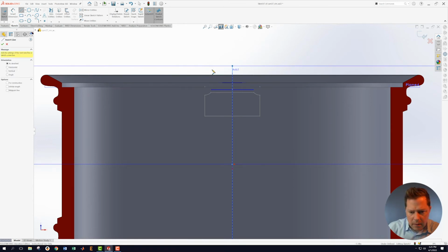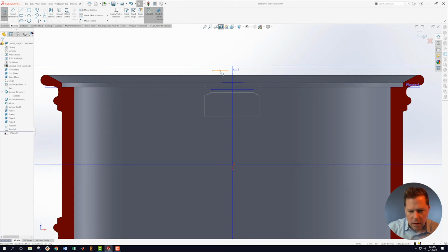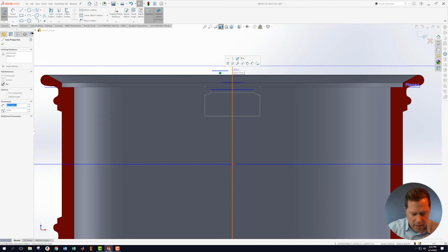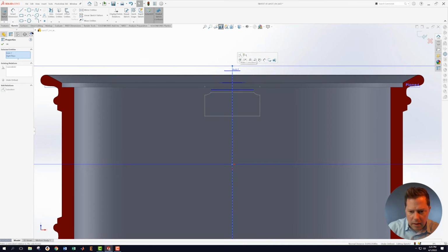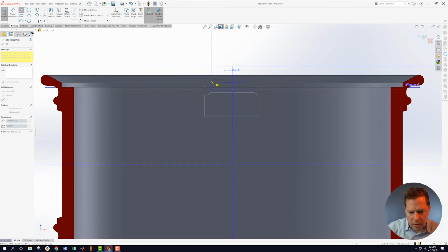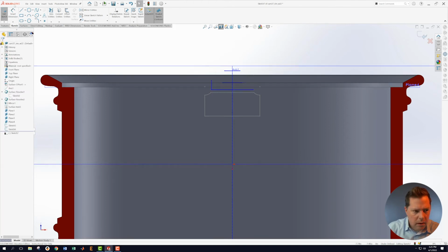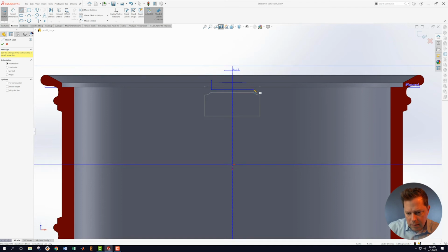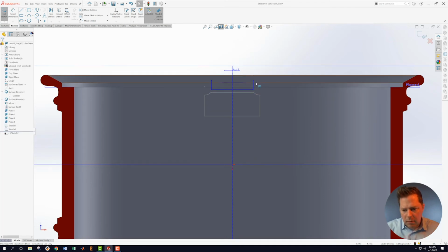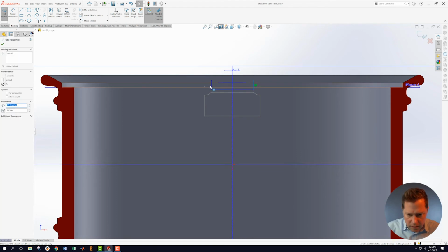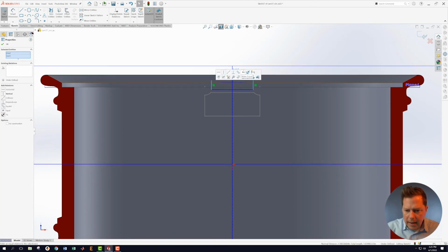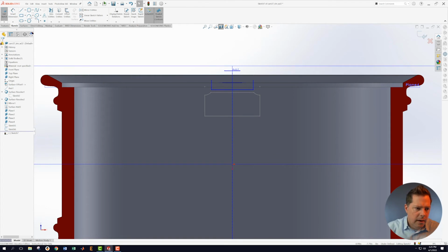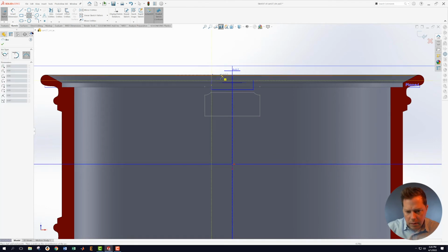Okay, I'm going to do the same thing at the top. Okay, I'm going to grab the center of that and my plane. Do that thing. Great, excellent. We're almost there. From here, we go up vertical. And I'm going to make another one over here. Here, go up vertical some amount. I'm going to make these two equal to each other. That means they're going to be equal in length. Then I got another 3-point arc from here to here.